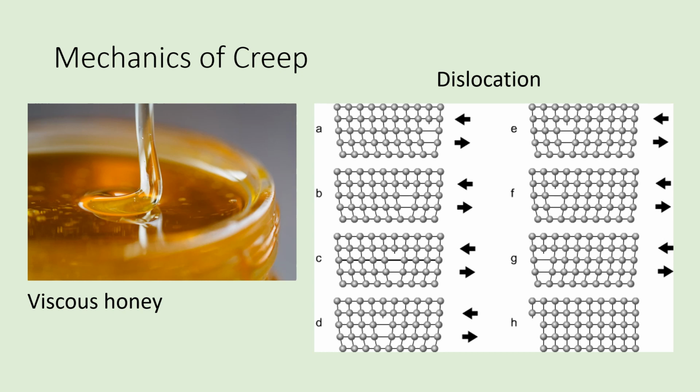And this is generally true for some amorphous solids such as silica glass or some polymers. In response to an applied stress, atoms or molecules in a material, or groups of molecules, move relative to one another in a time-dependent manner, resulting in creep deformation occurring.